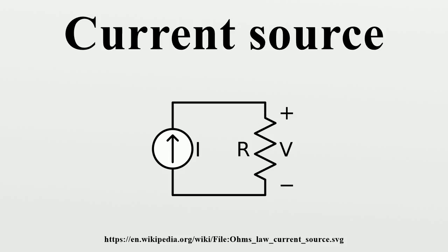The simple resistor current source will become ideal if the voltage across the load is somehow held zero. The idea seems paradoxical since real loads always create voltage drops across themselves, but it is implemented by applying a parallel negative feedback. In these circuits, an op-amp compensates the voltage drop across the load by adding the same voltage to the exciting input voltage.